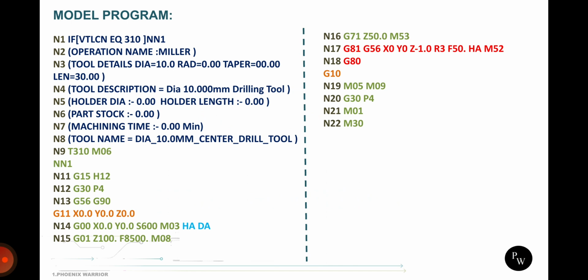So many Poka-yokes are followed in so many softwares, like in Fanuc i series. They are using some Poka-yoke lines. So depending upon the programmer, the Poka-yoke line will be changed. In so many softwares like Fanuc and Siemens, they are using G40, G80 and G15. So it is for Poka-yoke. In case the previous program doesn't switch off the cutter radius compensation or any other datum shift, then the same effect will replicate in the continued program. So then the actual program will run in a very wrong way. So that's why they are using the Poka-yoke lines.